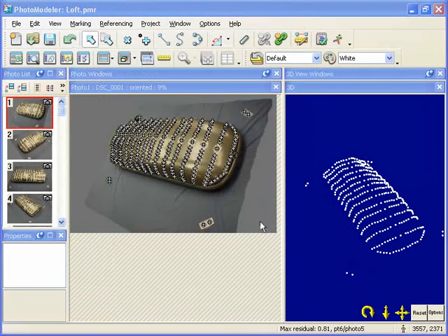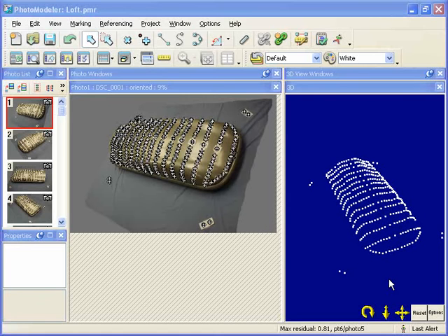In the previous section, we showed a fully automated method for producing a point cloud model. Now we will demonstrate the automatic tools used independently, instead of all tied together in an AutoProject. We'll first show auto marking and then auto referencing. This is useful if you do not have the coded target module, or for performing each step of an AutoProject individually to help find errors or help fine-tune automated project setups.